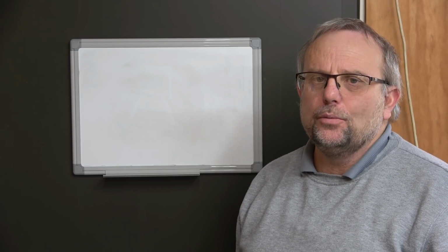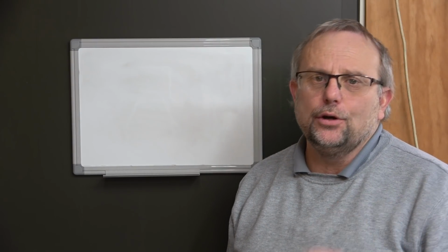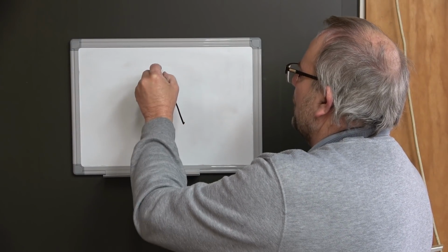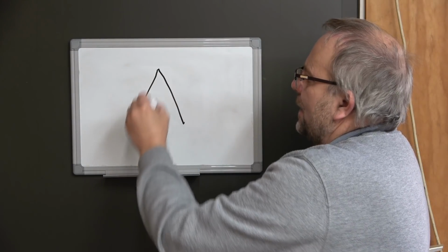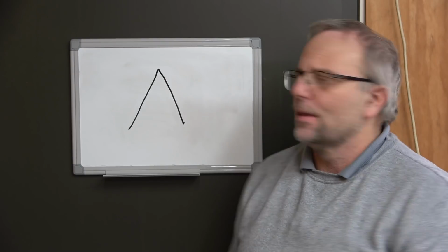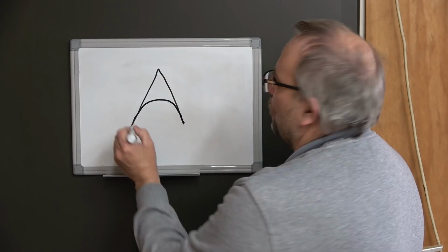The final parameter we need to look at in constant velocity is the angle at which constant velocity turns off. So imagine if you are machining something like this here. If you want to go all the way up to that tip there, then you're going to need to turn the constant velocity off. If you don't, it's going to come up here and it may cut the corner like that.